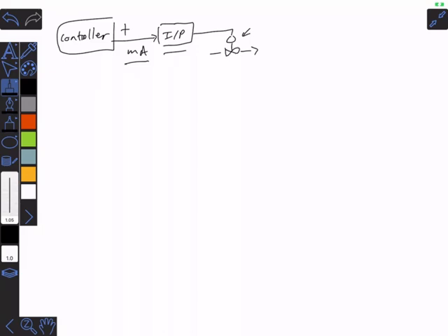Is everybody following me on that? And so on a high level, it's actually what I really want to be doing. I want to be thinking about it that the controller causes a change in flow. That's the zoomed out level. But on the low level inside, the way that happens is the controller outputs a milliamp signal. The milliamp signal is converted to a pressure signal. The pressure signal gets sent to a pneumatic valve. The valve either opens or closes depending on the sense of the valve. And the flow results from that.